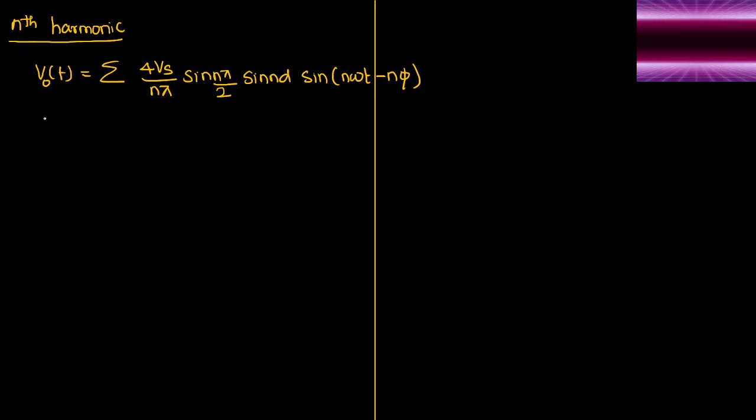Similarly, if you want to write the expression for the nth harmonic impedance, the value of resistance will not change with respect to harmonics. But harmonics deal with frequencies. We also know that when we are discussing the third harmonic, the output waveform will be 3 times the actual waveform, so the frequency will be tripled. If the fundamental is 50 Hz, then the third harmonic will be 150 Hz. So the frequency keeps changing when the harmonic value changes. These harmonics are directly affecting the frequency.